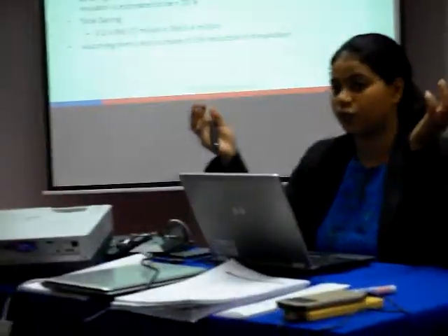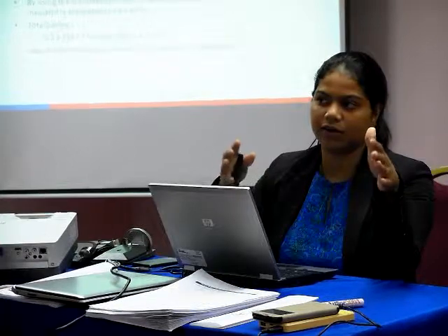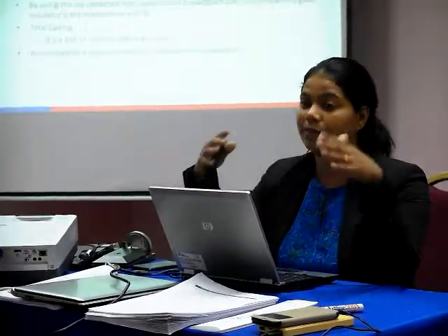So why do this? Why do we need to do this project? Benefits of it. First, of course, it will reduce the unplanned outages. As we have seen earlier, 63 failures in 3 years. So hence, by doing this, of course, we can improve the SAIDI. And also the second one, by predicting the life of this cap and pin insulator using the UV imaging method, we can detect problems at a very early stage instead of just waiting for it to fail. We can do something about it.